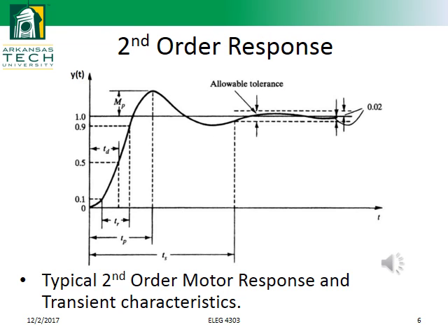For the transfer function, we're going to be looking for a second order response with a specific settling time, which will be discussed next. Settling time will be shown by reaching 98% of the steady state. We'll also be looking for a percent overshoot, which will be shown by the M sub P, which will be how far we go past our steady state. Also will be discussed in the next couple of slides.